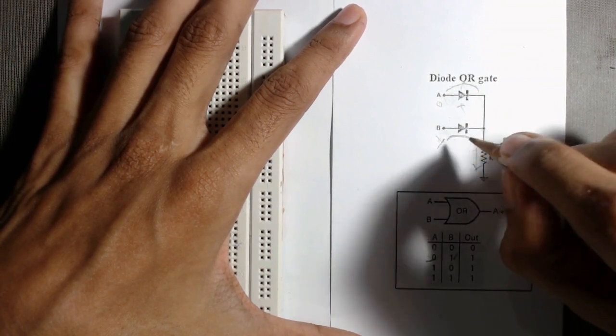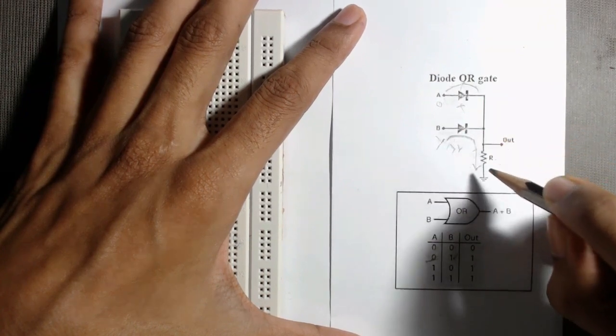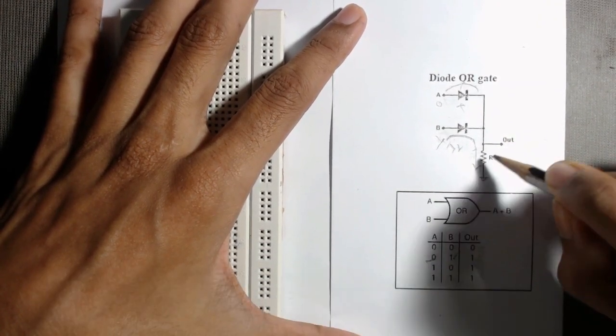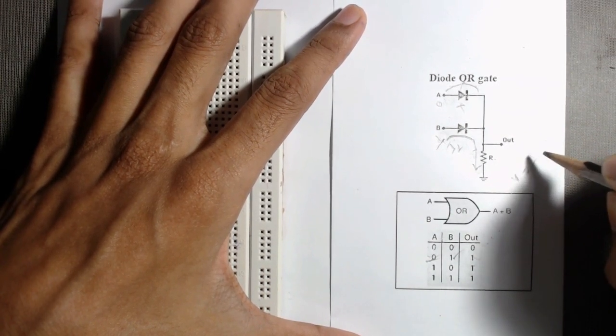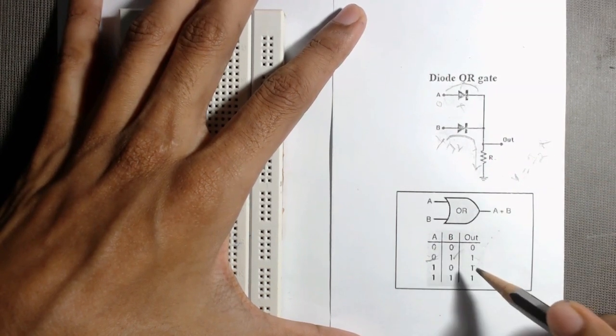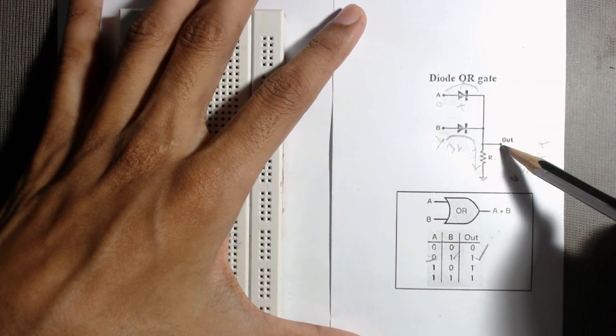Suppose I2 current is flowing through this diode, so I2 current will also flow through this resistor, so output voltage across this resistor will be V equal to I2 into R. So we will get output 1 in this case.